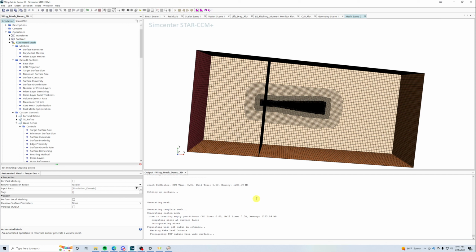This does happen to be one of those cases. An airfoil at low angle of attack, there is some disturbance in the flow direction, pretty minimal, right? The flow is largely going in the X direction, even when it's near the surface of the airfoil at the top or bottom. If it's not at the very front, it's probably largely going in the X direction. So airfoils at low angles of attack, pretty damn good use case for a trim cell mesher.